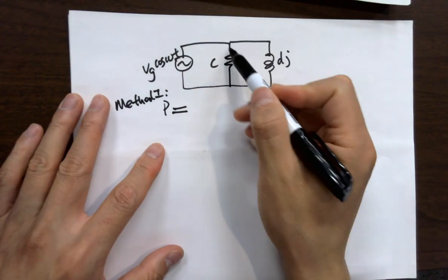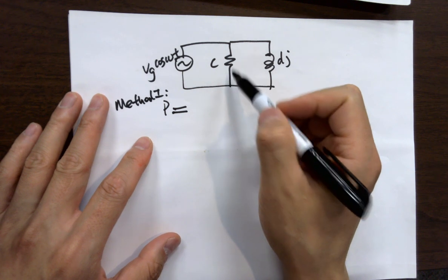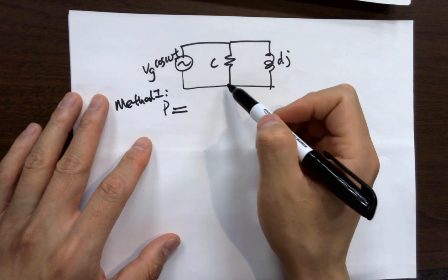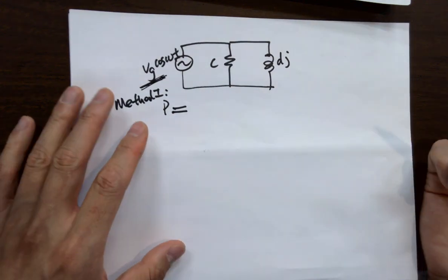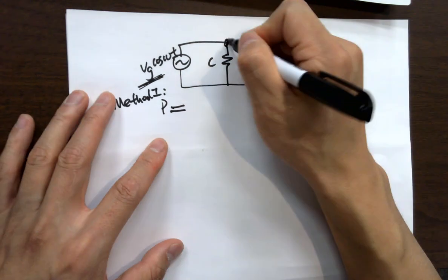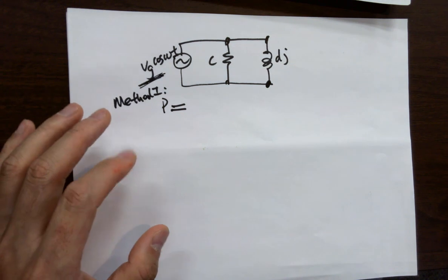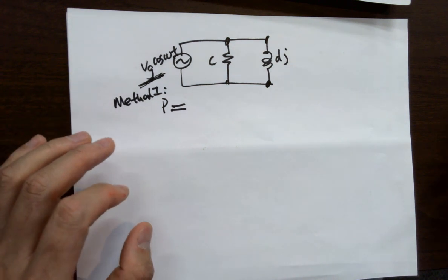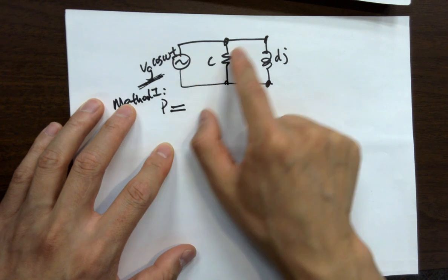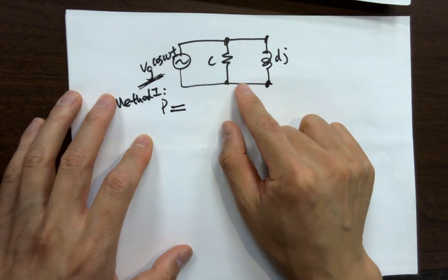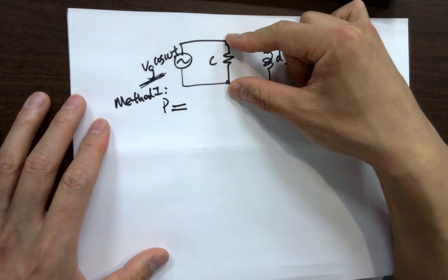So we need to know the VRMS and IRMS across this guy. Okay, so what are they? That's the peak voltage, sine wave. This exists here and here. Okay? Any difference? No, it's a wire. It's a wire. No difference. It's going to be the same Vg cosine omega t. Right? So now let's look into this resistor only. I think we'll be done after that.